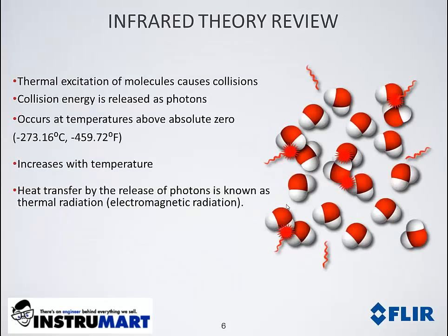Now, because our discussion today focuses primarily on infrared radiation and infrared cameras, let's review a little infrared theory. And we're going to start at the molecular level. Now, a medium or material, and that could be a fluid, a gas, or a solid, as that medium heats above absolute zero, absolute zero being minus 273 degrees C or minus 460 degrees F, the molecules within the medium start to move.